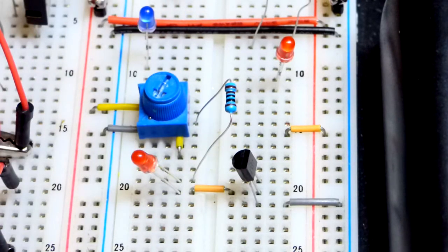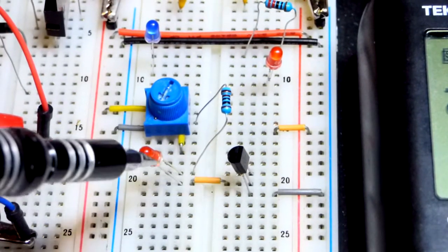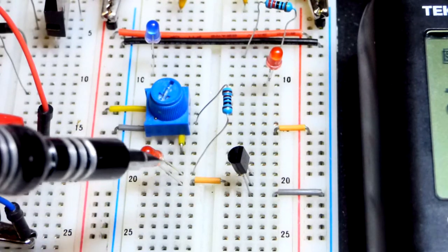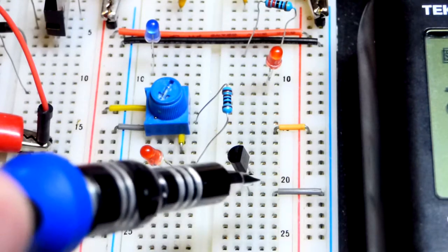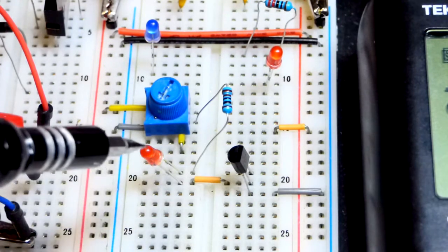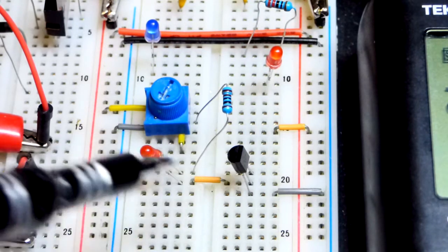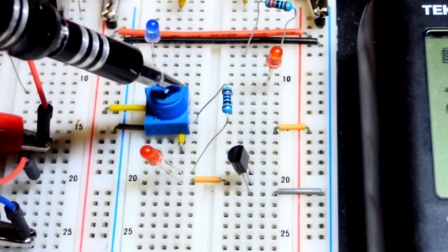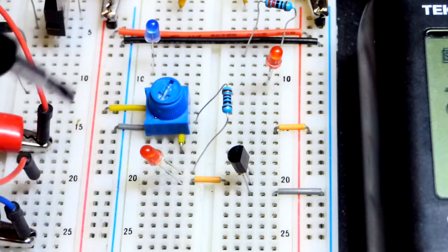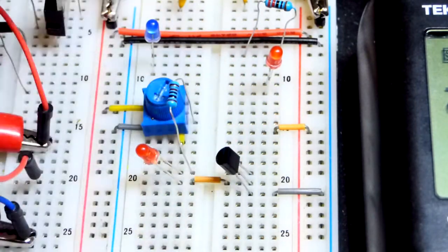It's not connected electrically. So the base of the transistor takes about 0.7 volts, 0.6 volts to start conducting, just like the LED takes about 1.5 volts to start conducting. As more current goes through it, it builds up a voltage of about 2 volts, and the base to emitter about 0.7 volts. So we can go from about 2.2 volts at a minimum, and they'll start conducting a little more after that. The rest of the voltage set by the trim pot goes against the resistor, but there's also the resistive element there. In any case, very little current. That is the main takeaway. That's why the LED did not get very bright.